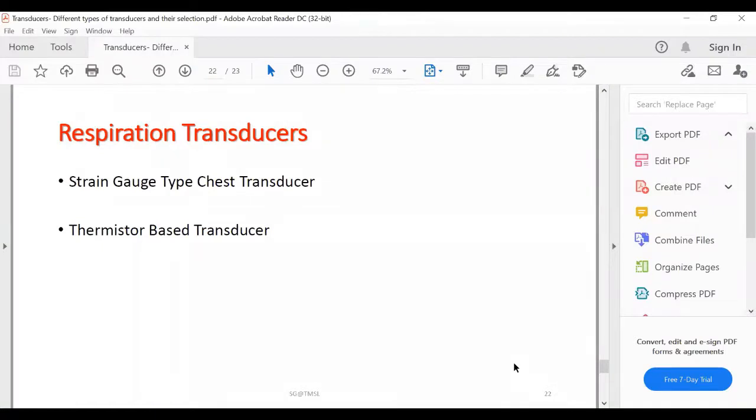The variation of its resistance in synchronization with the respiration rate, as a result of the cooling effect of the air stream, can be detected. This thermistor is connected to a voltage dividing circuit or a bridge circuit, whose unbalanced signal gives the respiratory signal, which is then recorded.